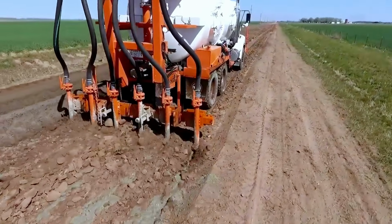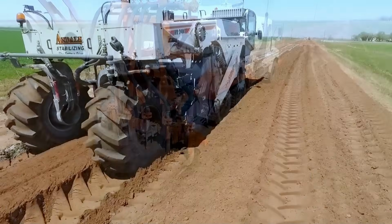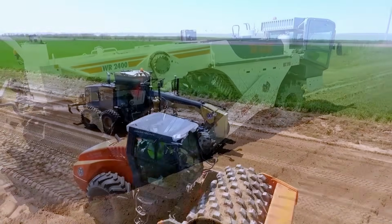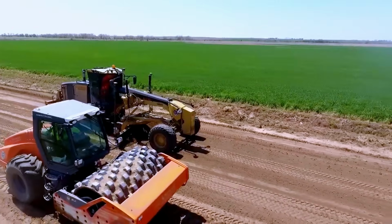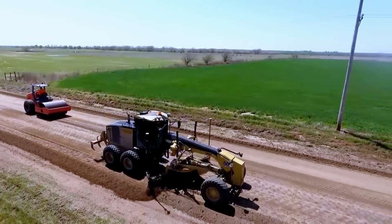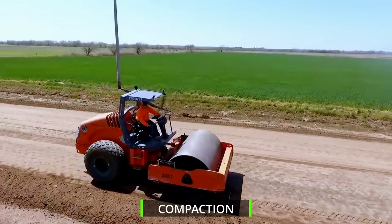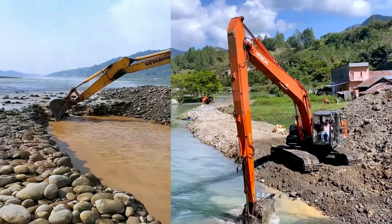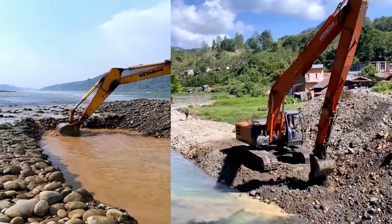Cement-bound subbase is a cost-effective method to construct a heavy-duty and durable pavement within a shorter time. It offers an alternative to traditional flexible materials. The binder material can be rapid-setting, such as cement, or slow-setting materials like PFA and slag. However, unbound granular materials are most commonly used for road projects.